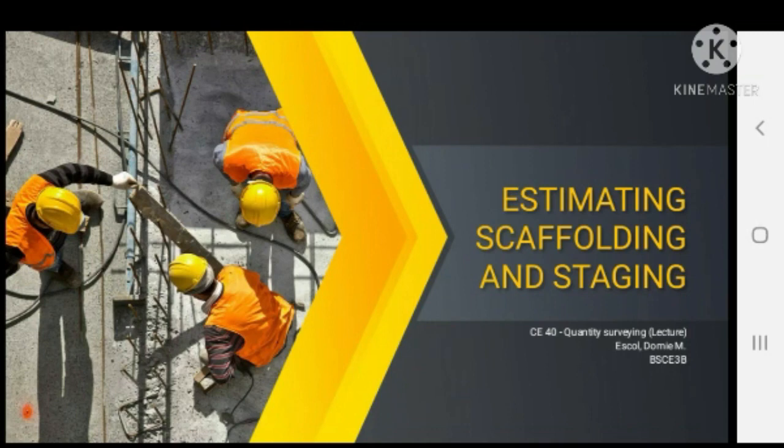Estimating scaffolding and staging. Estimating the materials for scaffolding and staging requires time and wider imagination, considering the different parts of the structure involved, such as the vertical and horizontal supports, the diagonal braces, plus the blocks and wedges, which are not shown on the dated plan of the building. The common practice of most estimators is to make an estimate of this item either by quantity of the materials or by lump sum amount in the bill of materials and cost estimate.